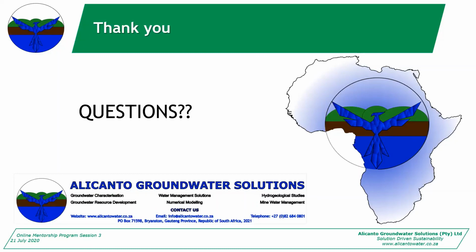Look, you can do that, and with a walk mag, it's useful to have. Your base stations help with any diurnal variations that you might have. If you're walking for like 3-4 hours at a time, you might go through a diurnal variation.